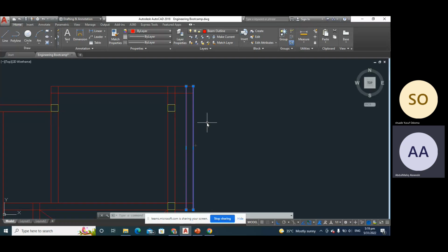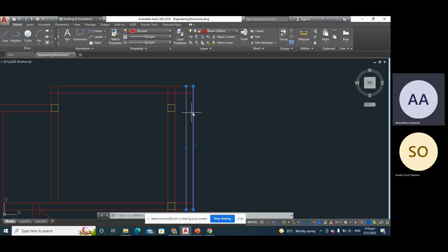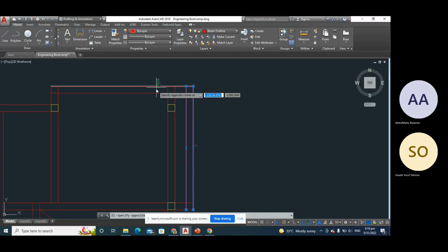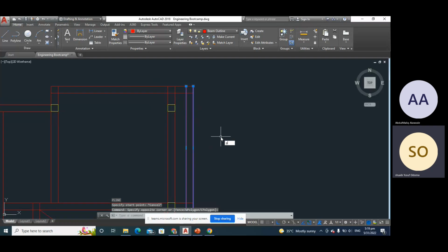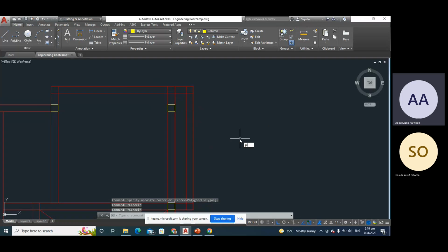Okay. So in a nutshell, this beam I've highlighted is actually the secondary beam at this junction. While the beam that I've just highlighted now is the primary beam, because it's going to be the one supporting this beam. If you draw your bending moment diagram for this beam, it's going to look like this.